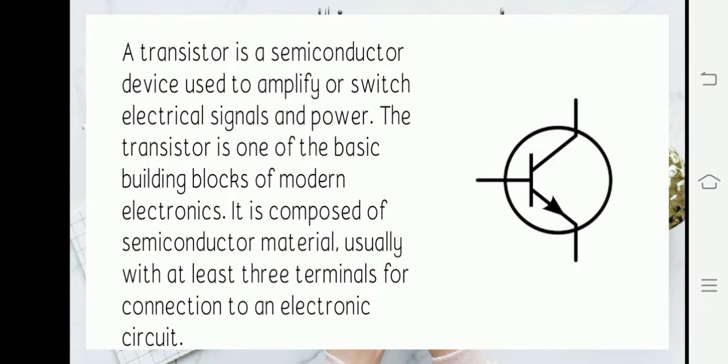The base-emitter junction is forward biased. There is a flow of electrons from the emitter to the base and holes from the base to the emitter. However, since the concentration of emitter electrons is greater than that of base holes, this current is primarily made of electrons. These emitter electrons become minority carriers in the base. However, since the base is narrow, very little electron-hole recombination occurs in the base and these electrons are drawn toward the collector-base junction.